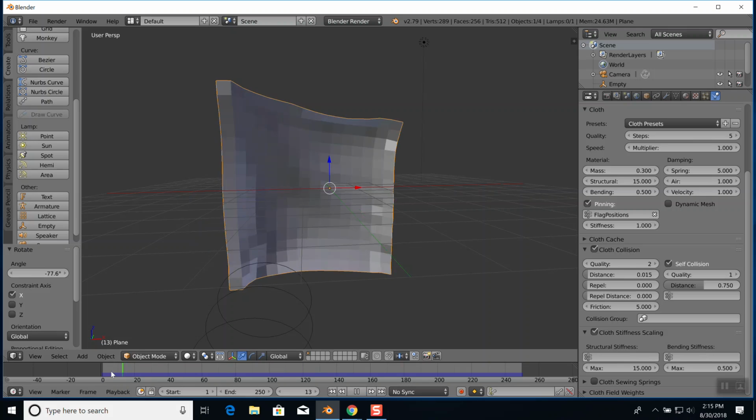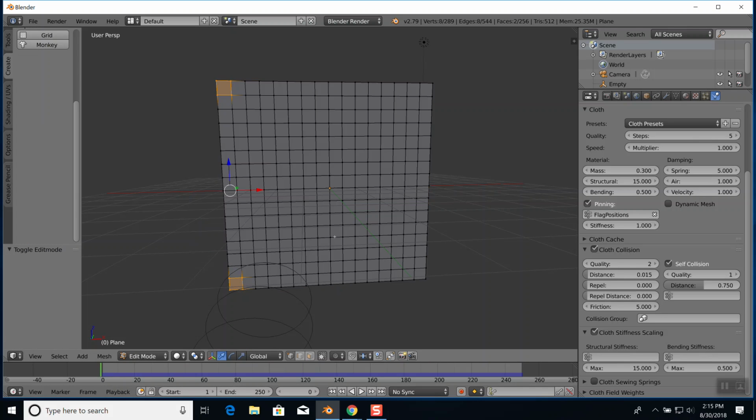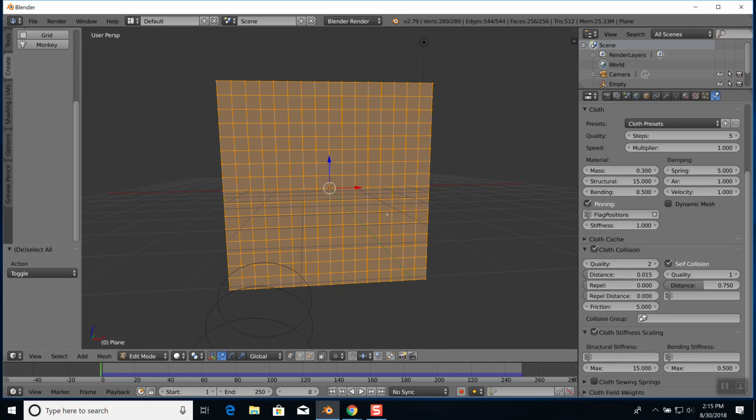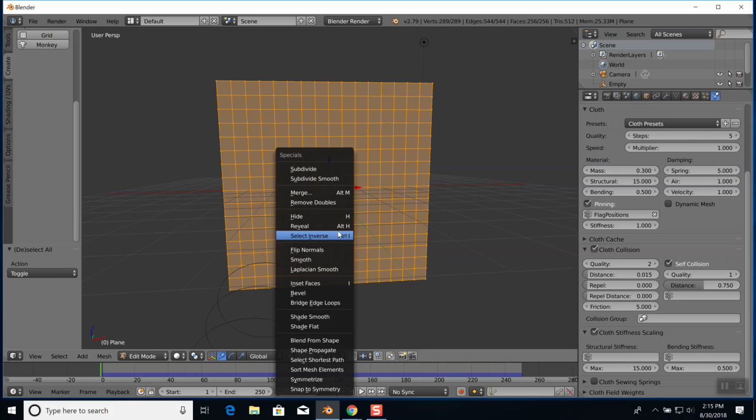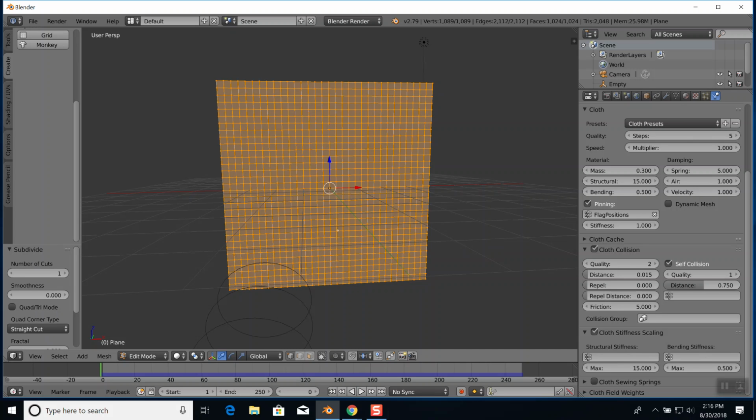And let's go create some more. I'm going to go into edit mode. So I go to W. And I'm not sure what this will actually do to our vertex groups, but let's create some more vertices. So I'm going to do an A to unselect, an A to select again to choose everything. I'll choose W, S for subdivide, and we got more places. Now you can achieve this without creating vertices.